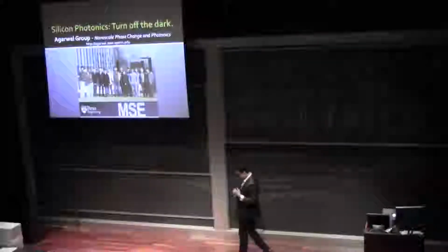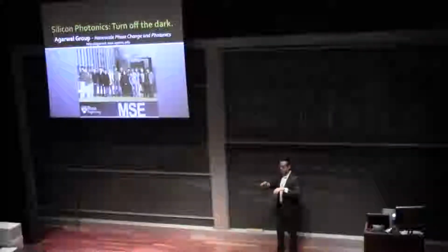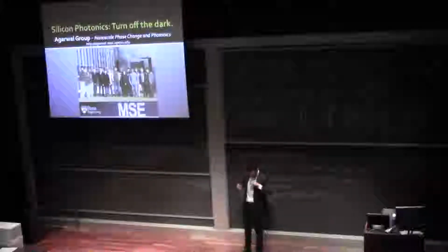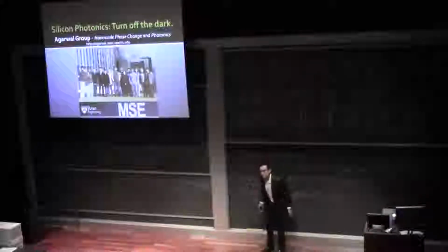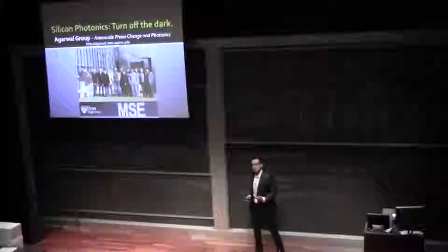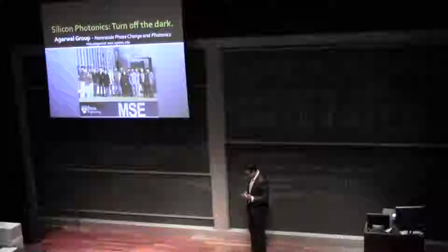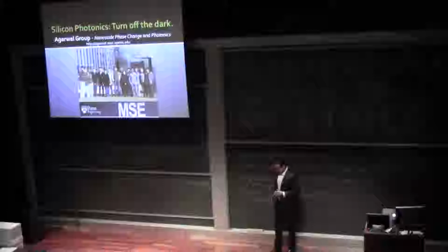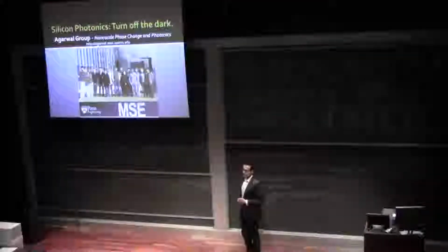So you're talking about the heating, for example, from the metal semiconductor system? You're absolutely right. So I'm going to explain that a little bit for the audience, but basically when you have a surface plasmon, when you have this electron light wave system, you're literally driving current, right? Your electrons are moving back and forth, so you're driving current in your metal and you're dissipating heat. And you're right. We actually have some studies that are coming out where we see that we can actually heat this thing by over 100 Kelvin, potentially. And all this requires is better design. We're going to need better heat sinks. So yes, that is something that we need to take into consideration.